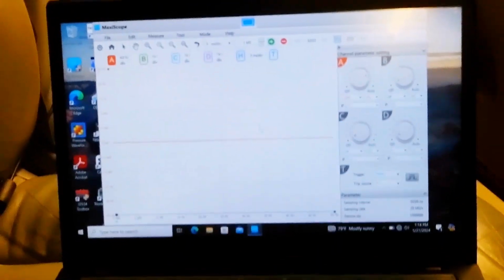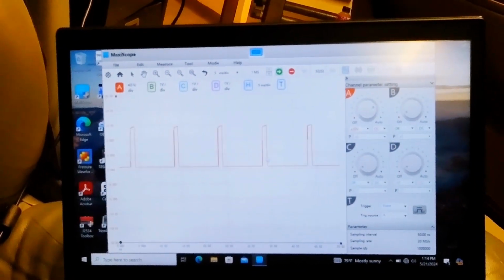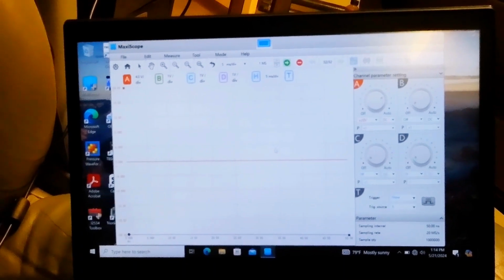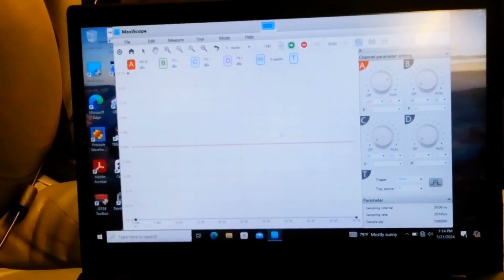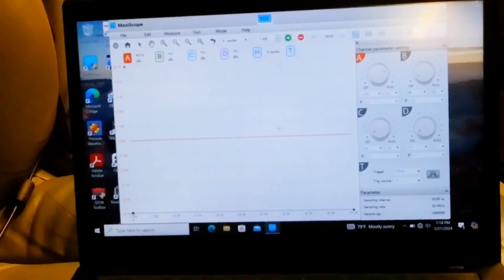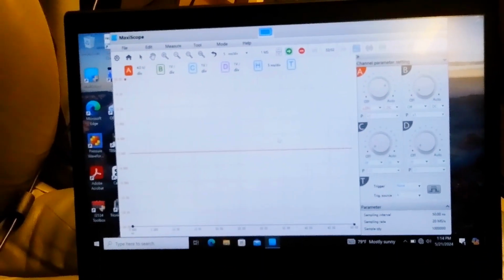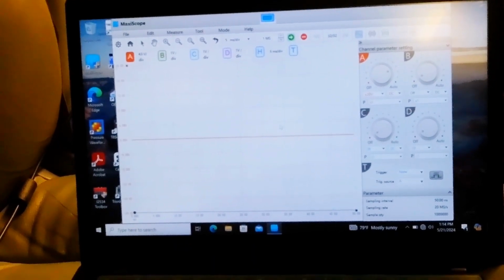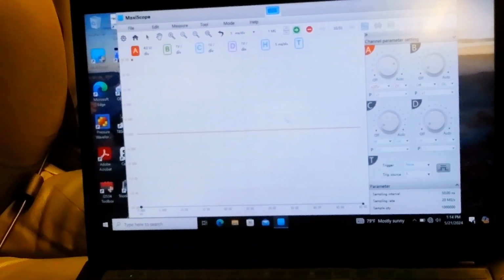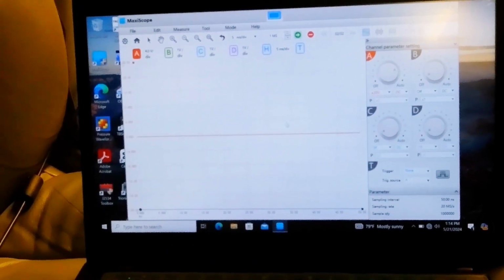That only leaves a couple of wires to check here on this module. We've already checked our ground. We're going to go ahead and check the positive feed. We saw positive voltage on that pin D. That means our motor has good connection through it, and we have a good positive voltage coming from pin E of this blower motor control module.